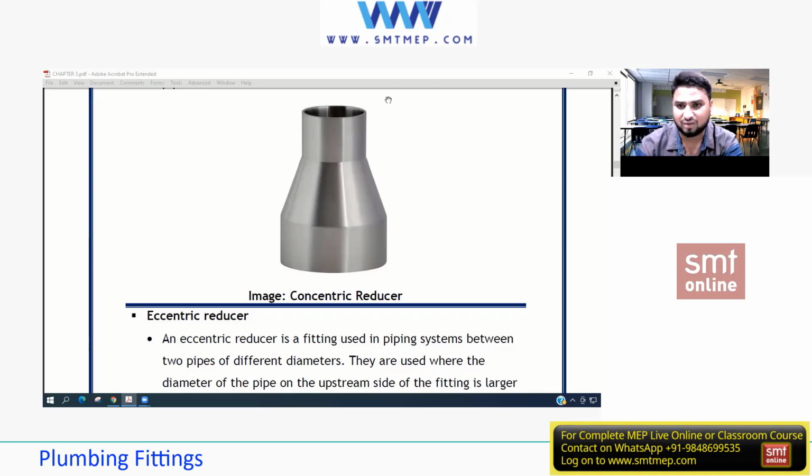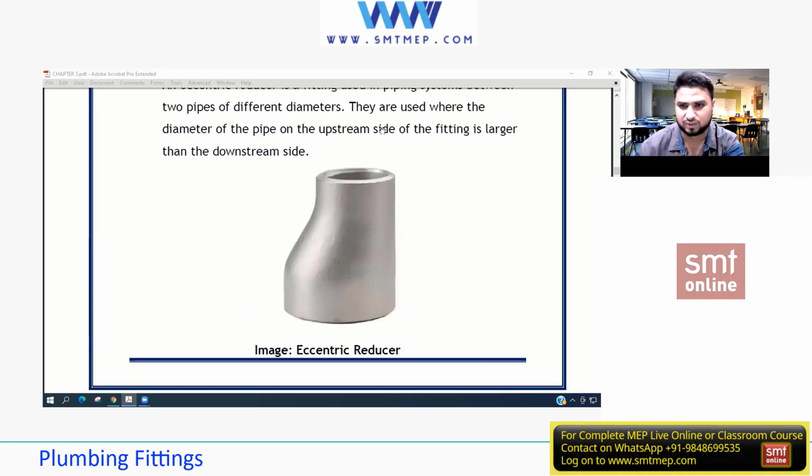Okay, to avoid that cavitation because of the air gaps, we use that kind of reducer over there. You can see, always in the suction side, so that the water goes in this manner. Okay, so this is where we use it nearby the pumping system or connected to the pumps. In the suction side, always remember, because of this, the water touches the surface of this, and there is no gap in between the material and this. So no air gaps and no air bubbles over here.